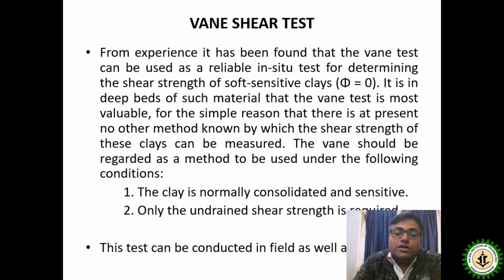But if the soil sample is so soft that we cannot collect it from the field, that time the vane shear test will be performed at the field itself. We have to bring our vane shear apparatus to the field, and there we have to conduct the experiment.